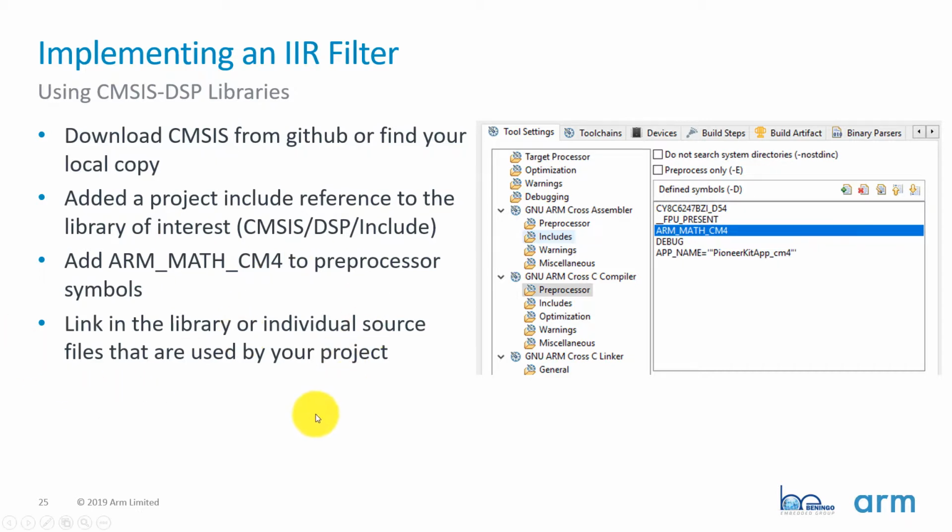And at that point, you can compile your code, deploy it onto the PSoC 6, and you could run the code and see how the test filter works, but then you could also attach the ADC inside of there and generate and actually push like a sine wave or something through it and see how the filter actually behaves. So it ends up being a pretty cool way, I think, to go from beginning to end to see the entire gamut of how things work. As I mentioned, though, I'm really leaving that to you guys to do today to actually try it on your own.